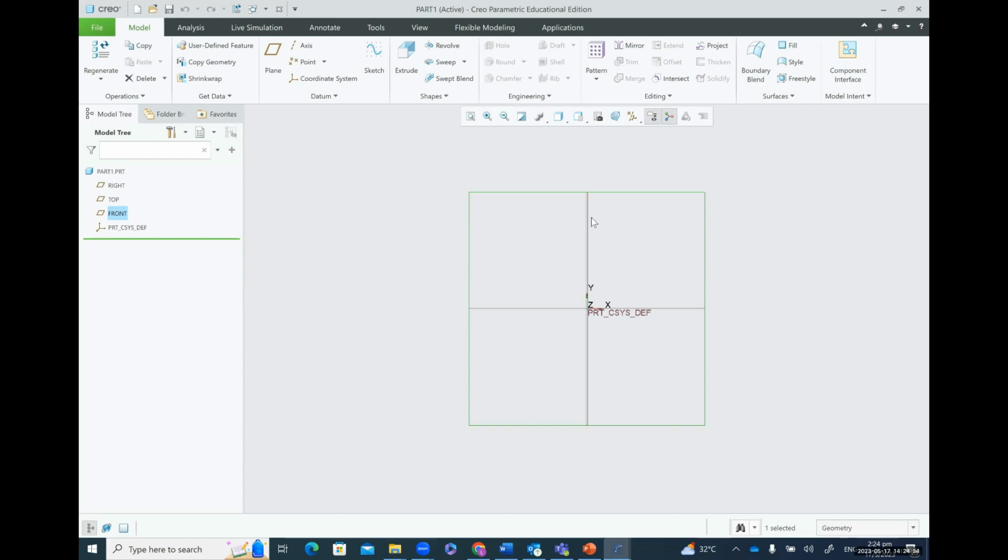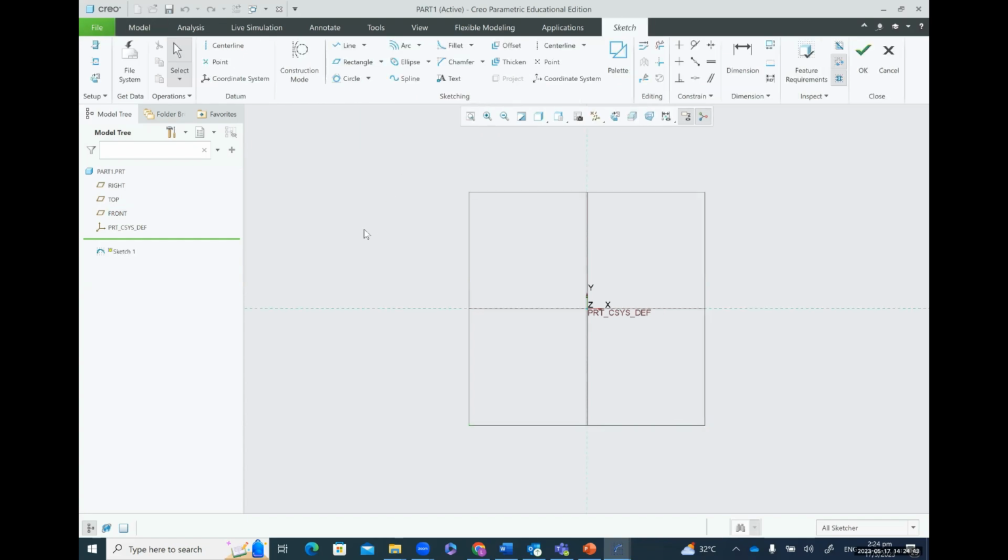So what you need to do is go to this sketch icon, click on it, and then it will bring you the sketch toolbox that we have seen before, right? So in these tutorial sessions, we will start by creating a very simple 3D structure, just a cuboid. Okay, so to draw a cuboid, first we need to draw a rectangle shape.